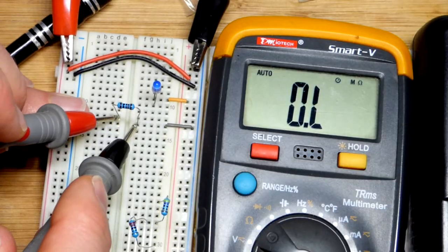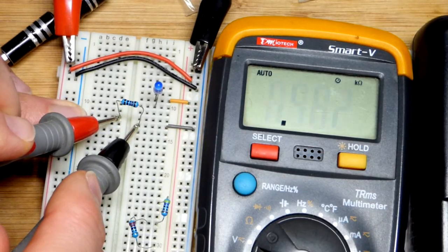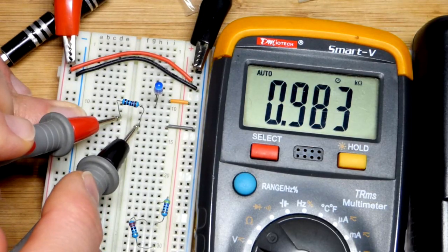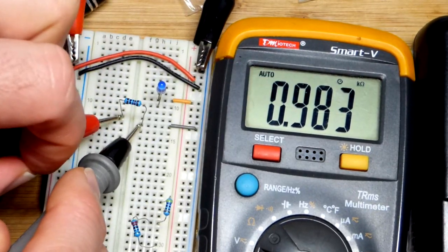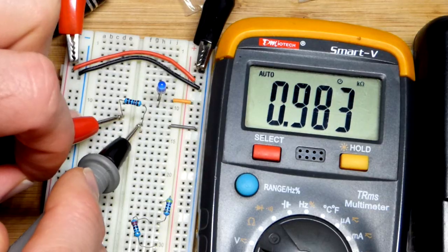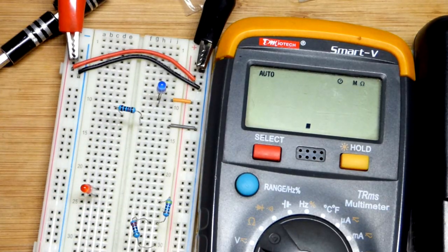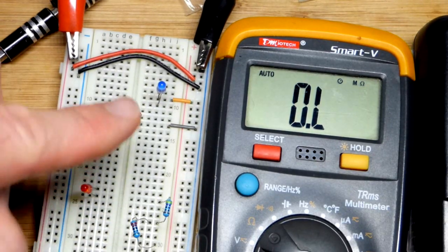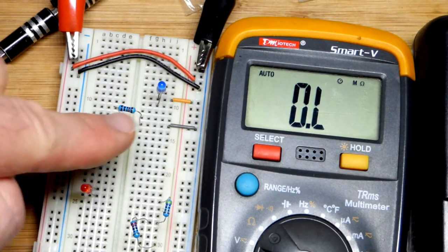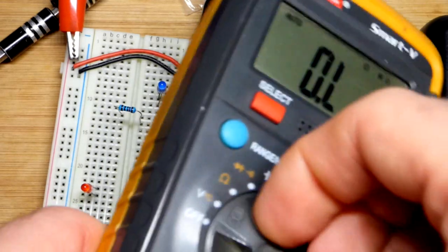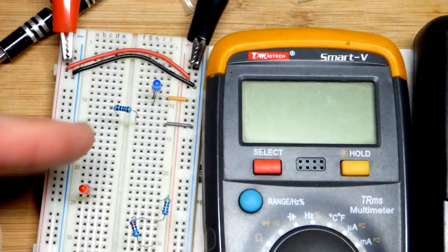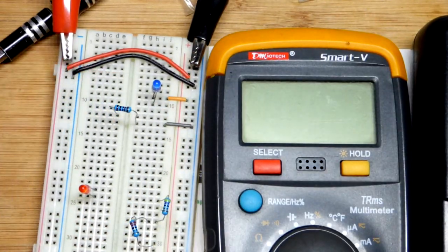So when you're first learning electronics, it's good to take all of these measurements right there. Get used to that. So that's in kilo ohms. So it's kilo up there, thousands of ohms. Probably a little bit shy of 1,000. But again, there's a 1% tolerance. And these cheap resistors, maybe even close to like 2%, since they're cheap. You know, you take that. And the difference between 1% off and 2% off is no big deal at all when it comes to most circuits.